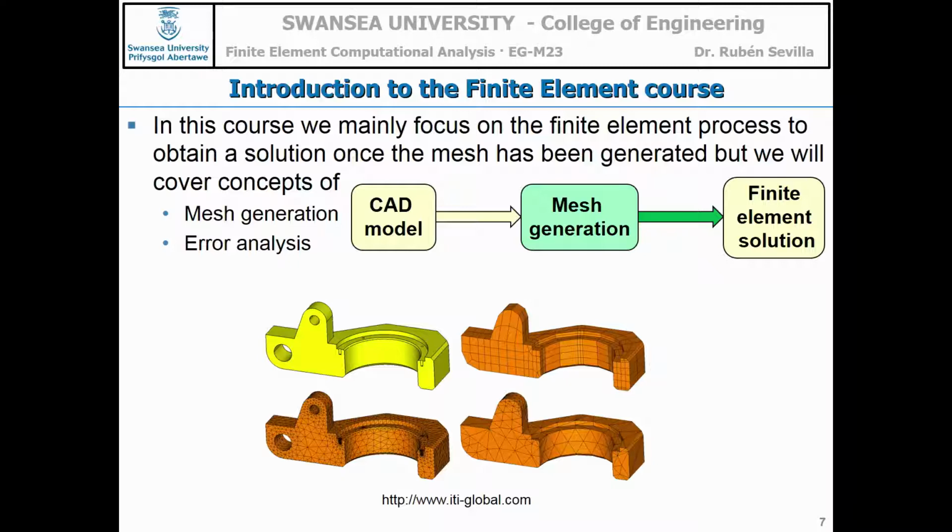Yeah. You know, as an engineer, that stress is going to be localized near the corners. So that makes sense to do this kind of meshes, where the elements are big in certain areas, but they are big in the areas where the stress is going to be pretty uniform. And the mesh is refined in regions where you are supposed to have stresses, right?